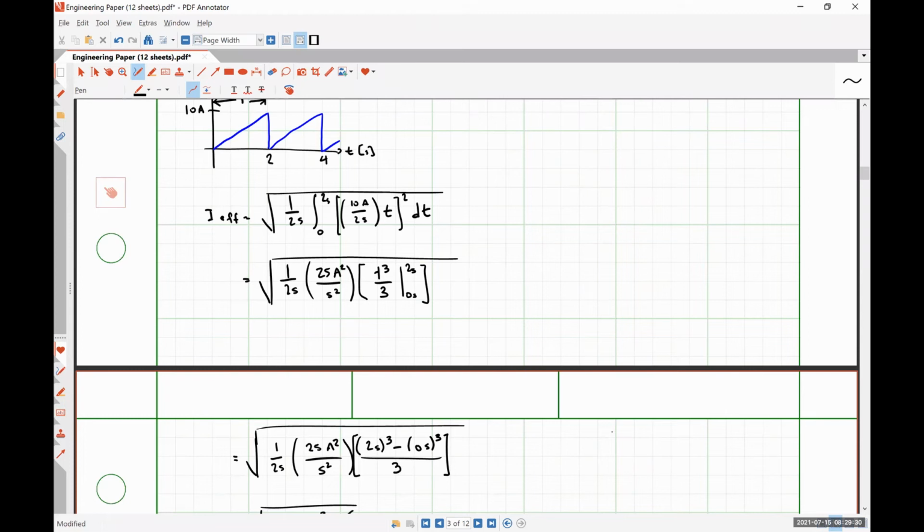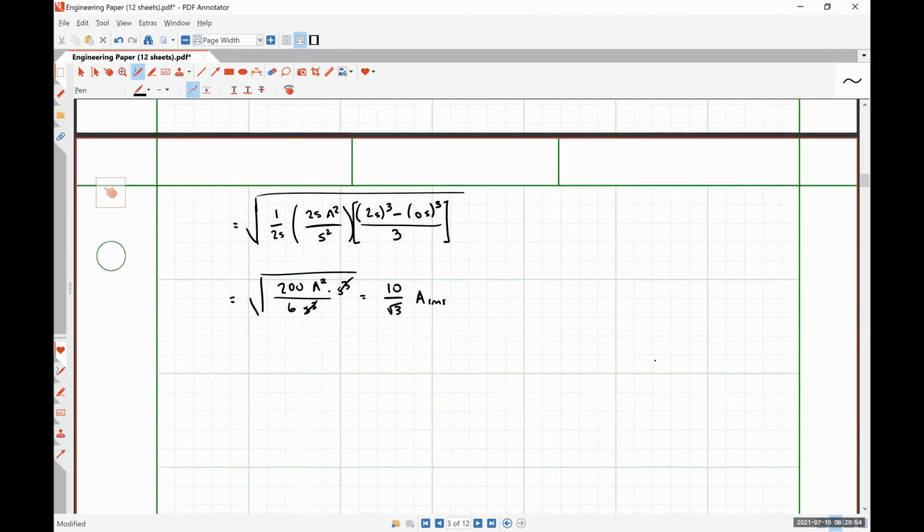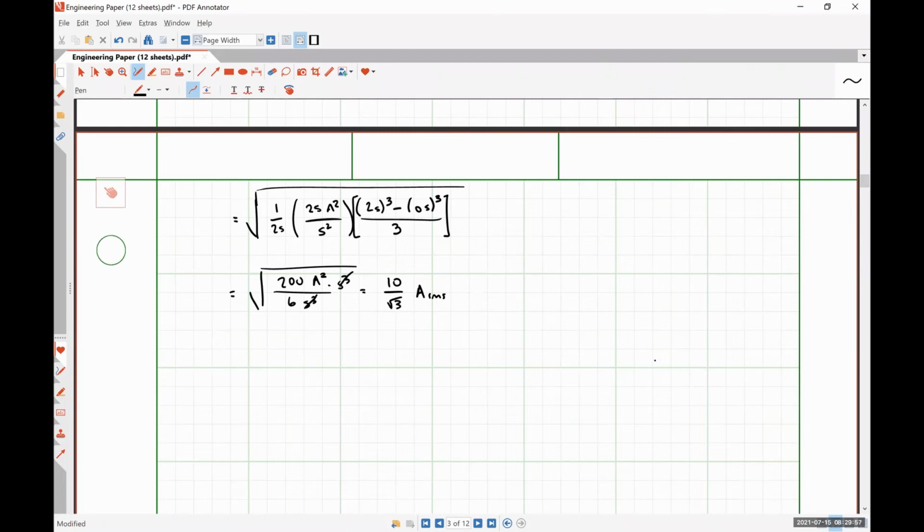So most of the waveforms that we deal with in electrical engineering, square waves, sawtooth waves, and as we're about to do, sinusoidal waves, actually have very, very trivial and simplistic effective values that we can really memorize and never have to go through it again. It's not until we get to more complicated periodic waveforms that we'll actually have to go through and calculate the effective value every time. So because we are in steady state sinusoidal analysis, it's probably of interest to us to figure out how this behaves, what the effective value is for a sinusoid.